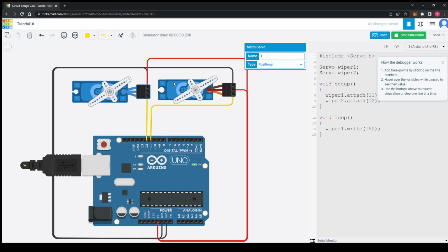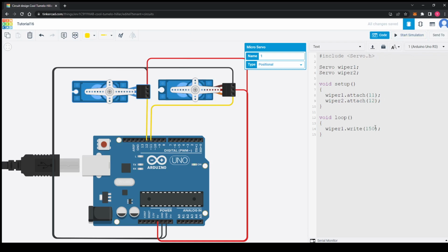So this is a basic command, guys. We should make it move, right? This is the first one. So obviously, this will stop. This is the default one, I think it is 90 right over here, and this will go till I think 150 right here. So we're telling the angle by dot write. We're writing its angle down in the Arduino memory and saying just make it go till 150 degrees. This is what the write command is. Just make it move. And in the parameter, we're passing in the angle in degrees.